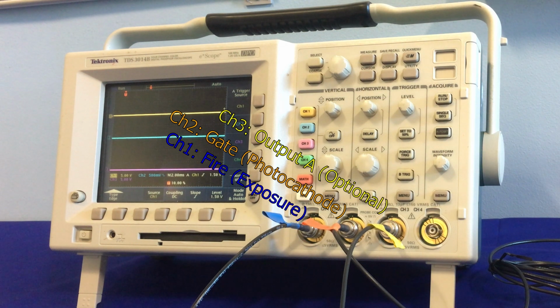So we've set our oscilloscope to trigger off fire pulse 1. That's our channel 1, our blue wire going into the oscilloscope. The impedances of all our cables are set to 50 ohms, apart from channel 2, which is our gate monitor. This is actually set to AC high impedance, and we'll see in a minute when we show this that we're just seeing the edges of the gate, not the whole gate, when we actually show it on the oscilloscope.